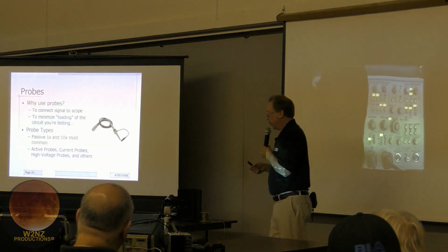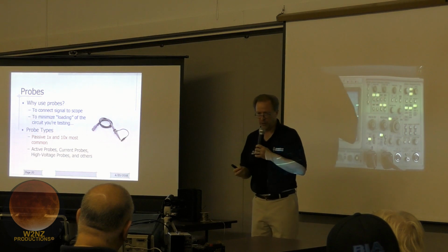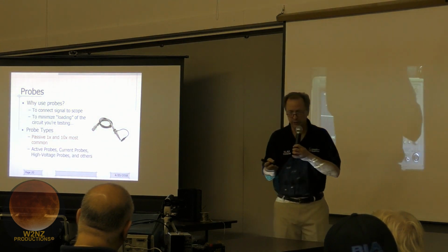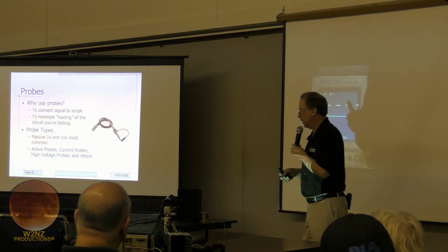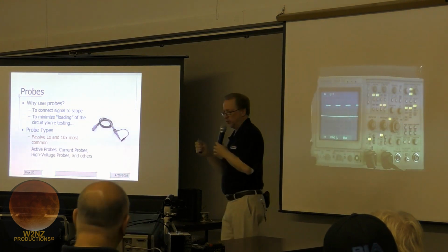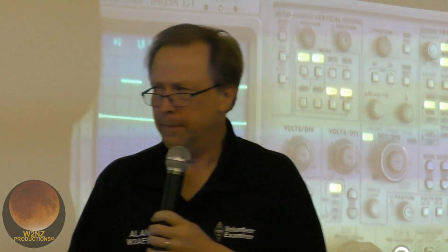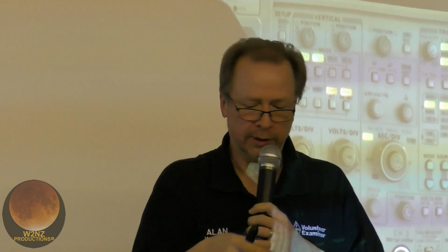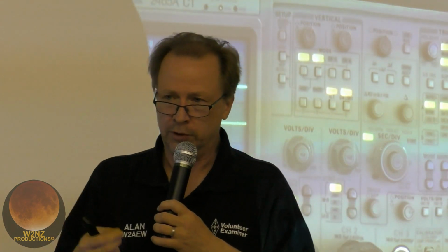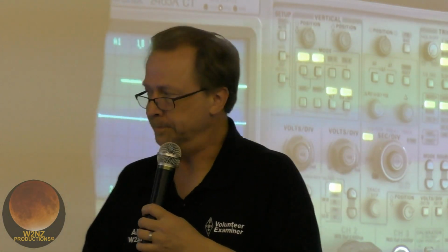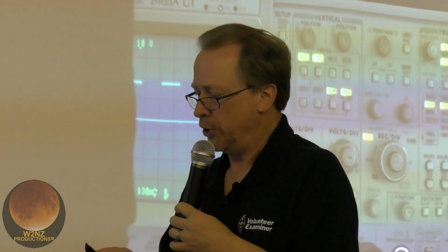So let's talk a little bit about probes, why we use them. Obviously, we've got to connect the signal that we're interested in somehow to the scope. When we're talking about RF signals, oftentimes we're going to come in with just coax off of a sampler or something like that. But when we're talking about probing into a circuit to actually understand or make a measurement to troubleshoot a radio or something like that, we're going to want to get in there with something just like we use probes on a multimeter. Okay? But there are some special probes that we'll use, and we'll talk about why.